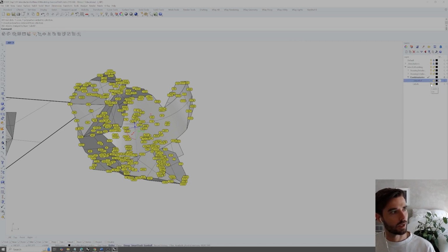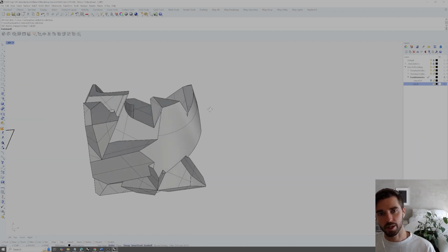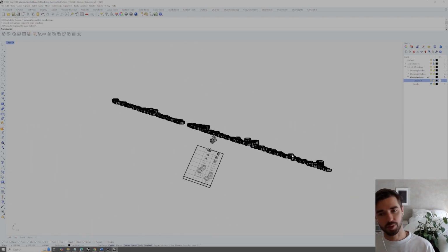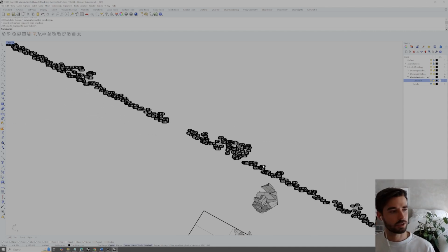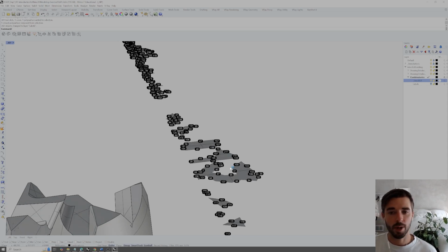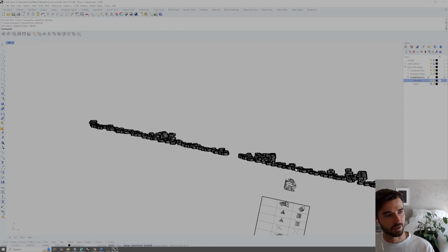Now we can actually just go ahead and turn those off for a moment. So you can see the complexity already in 3D, but if we turn on our unrolled surface, you can see how quickly it becomes complex and difficult to deal with. So cleaning up and keeping clean geometry in these early modeling processes is going to be critical. So you might want to spend just as much time in cleaning up geometry as you may in actually designing or kind of aggregating or constructing the geometry itself. So cleaning up will help you so you don't have quite as many surfaces unrolled.